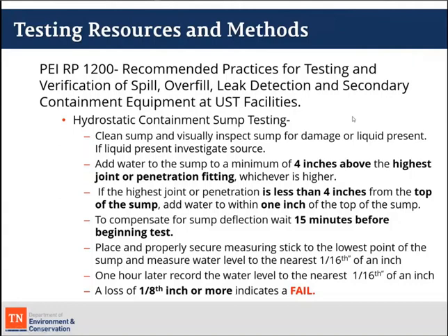So, probably the most popular form of containment sump testing is the hydrostatic test method. This is just a real quick snapshot of RP 1200's test procedure. I wanted to go over it because there are some different situations, and I put together some diagrams. I'm a visual person, so hopefully that will help in performing these tests, especially if you haven't performed a sump integrity test before, to make sure that you're doing these tests correctly and that they're valid.